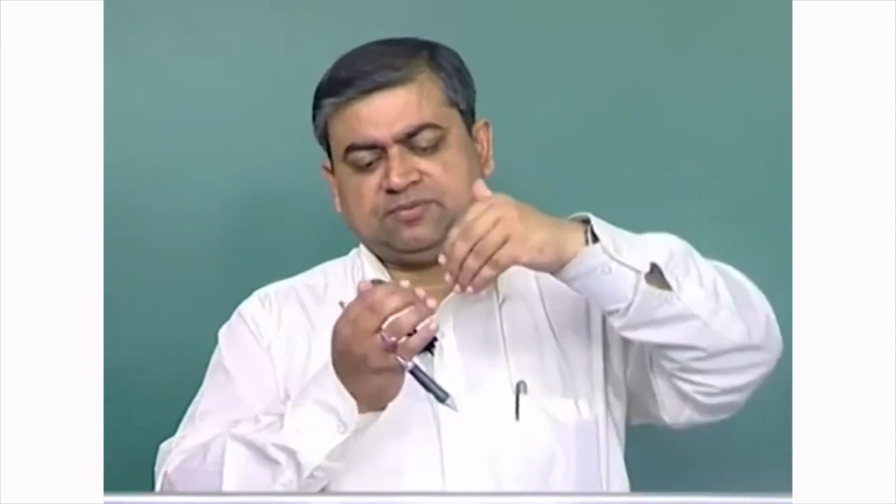So, if there is a difference because of a rapidly approaching tool, in this rate of dissolution, then there would be a tendency of the two surfaces to touch each other, and when it comes to just about touching, there is this sparking phenomenon, which is essentially an ionic discharge, which would happen because of the very small hills and valleys produced on both the surfaces, that is the tool and the workpiece surfaces, getting in very close proximity to each other.